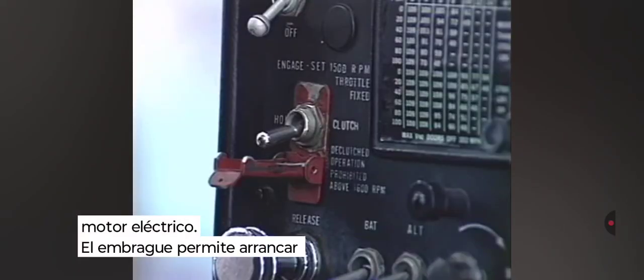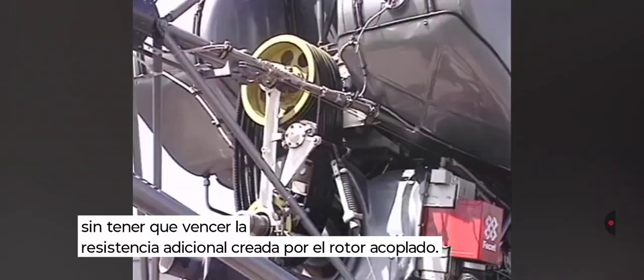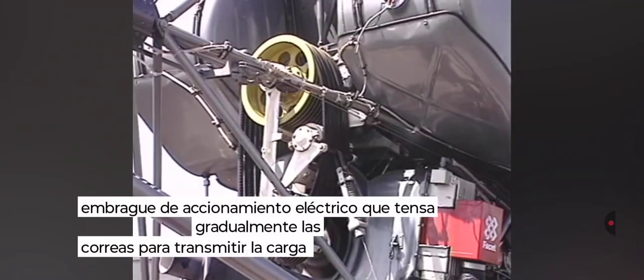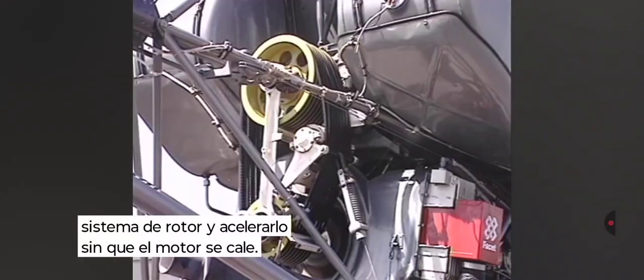The clutch allows an engine start without having to overcome the extra drag created by an attached rotor system. Here you can see an electrically actuated clutch gradually tightening the belts that will bring the load of the rotor system online and up to speed without stalling the engine.